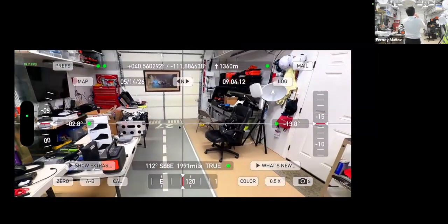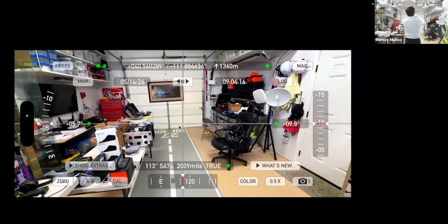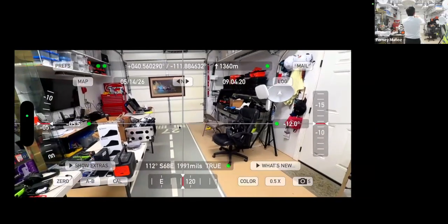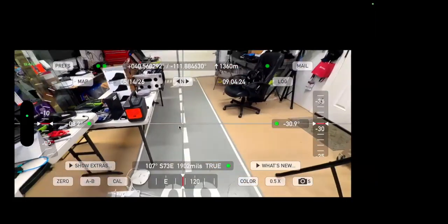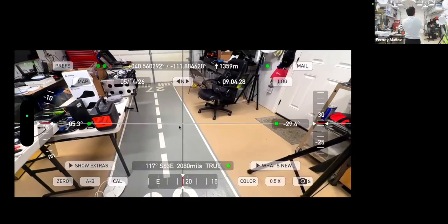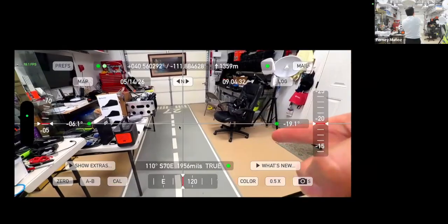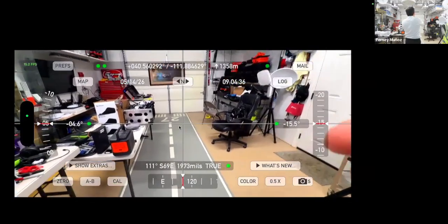Then this gives me how many degrees. Look to the right where it says 10 degrees, minus 10, minus 7, minus 6. Can you see there? Somebody give me feedback so that I know you're following me. Yeah. Okay, see where it says minus 30? Then that means that from the horizon, that antenna is tilted 30 degrees down. Okay, that's like right here. This is minus 20, minus 15.